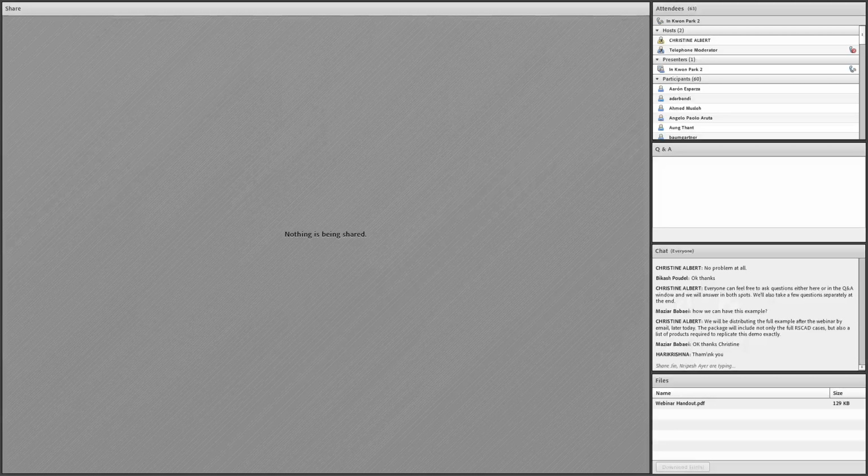Then the next demonstration I want to share with you is the real closed loop testing of a Texas Instruments DSP and RTDS. The simulation case would be the same as this standalone STATCOM case, regarding the operation of a STATCOM. But instead of having everything in your simulation case, the control part would be implemented on a DSP, and we will see how we interconnect that DSP-based control with the RTDS through the GTAO card and the GTDI card.